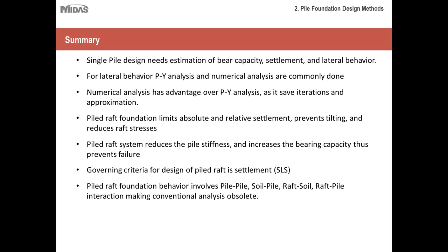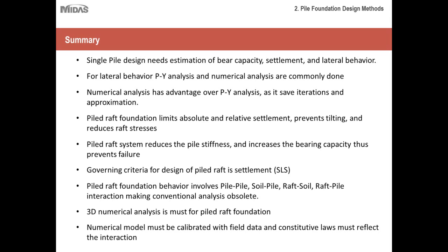Pile raft foundation behavior involves pile-pile, soil-pile, raft-soil, raft-pile interaction, making conventional analysis completely obsolete. Hence, a 3D numerical analysis should be performed and it is a must for pile raft foundation. And last but not the least, the numerical model thus created must be calibrated with field data and constitutive laws must reflect the interactions correctly.